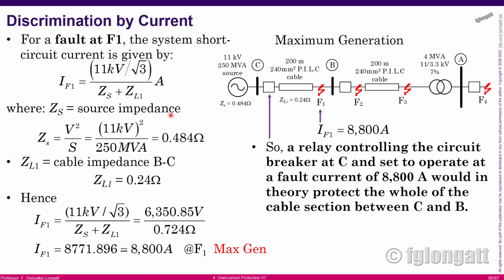What I will do at the very beginning is, let's calculate. Let's put some numbers about the short circuit current at the location F1, okay? F1 is the location at the very end of cable 1. It's very simple. We divide the voltage by the equivalent impedance using Ohm's law, and that will be the impedance coming from the external grid plus the impedance coming from the cable, okay?